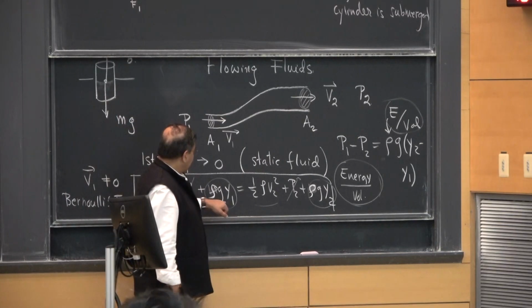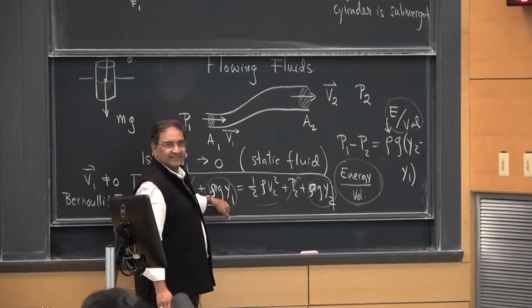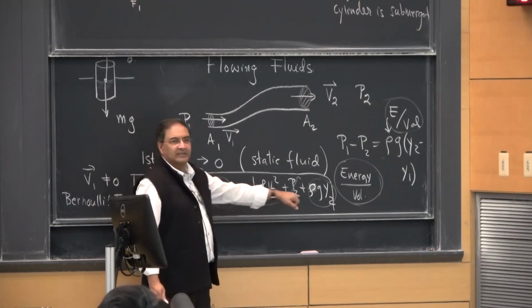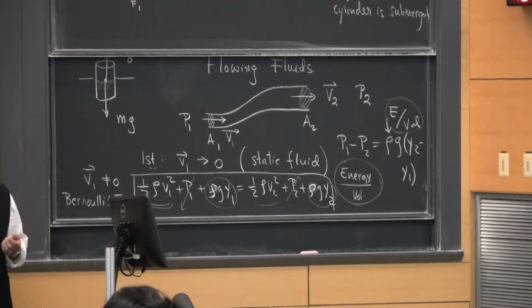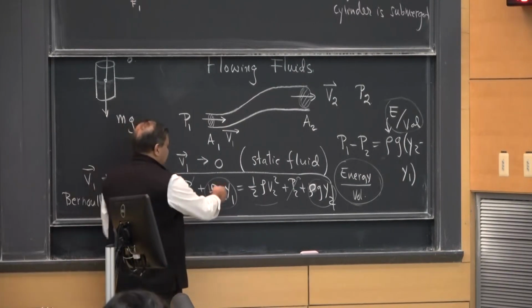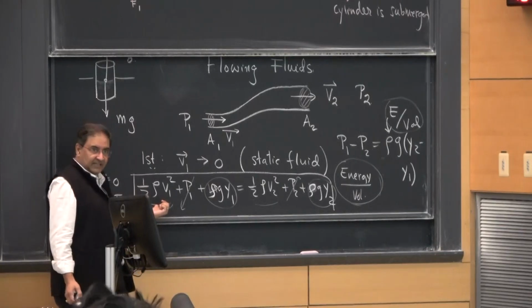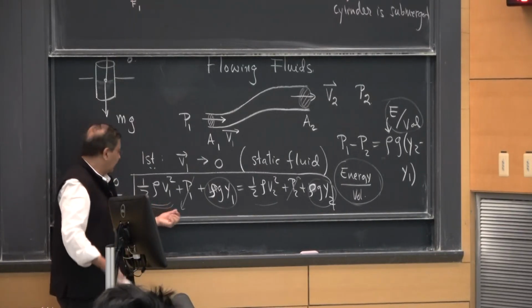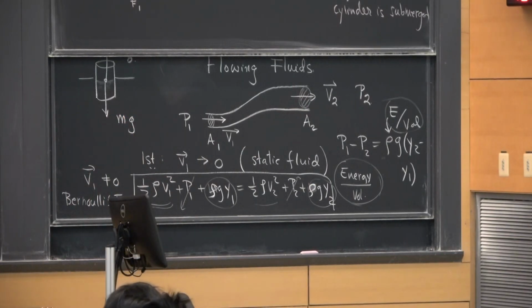So what I'm saying is that inside the body, y1 and y2 is roughly the same. As far as fluid density is concerned, the y1 and y2 contribution will be very tiny because fluid density changes very slightly, imperceptibly. So as far as the body example is concerned, you can drop these two terms, which means you are left with the kinetic energy density term, density meaning kinetic energy per volume, and the pressure term. If you raise one, your pressure goes down. Okay, let's go to the